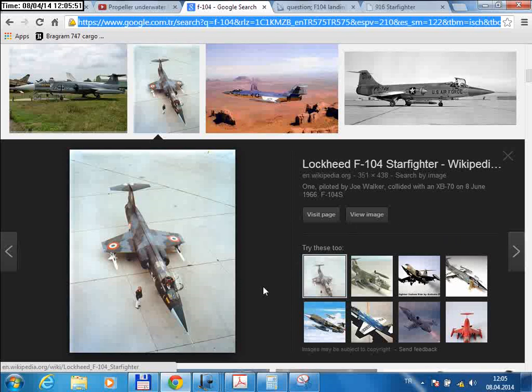So that's the disadvantage. Again, you see that if you want to improve something, you have to give up something else. While a very high wing loading is a good thing for high-speed performance, the same thing becomes a disadvantage for landing and takeoff.